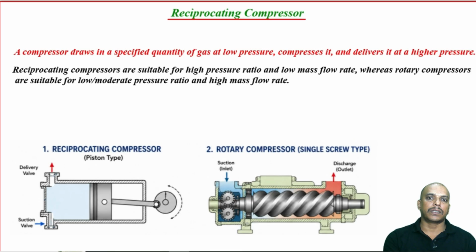We can classify it as a reciprocating compressor and rotary compressor. Now, in a reciprocating compressor the action of the compression is reciprocating, whereas a rotary compressor will have a rotary action in order to compress the fluid. Now, the fluid can be any gas. Generally, we can talk about air. Okay, we have seen air compressors. There can also be compressors where refrigerant, for example, vapor compression refrigeration system we have seen, where refrigerant will be in the gaseous state when there is compression.